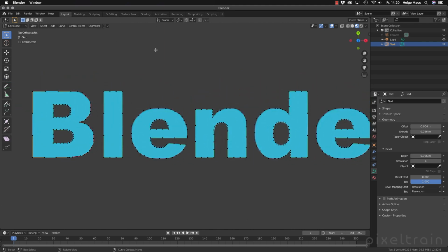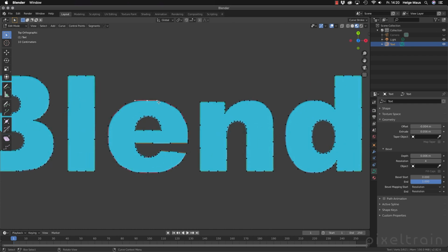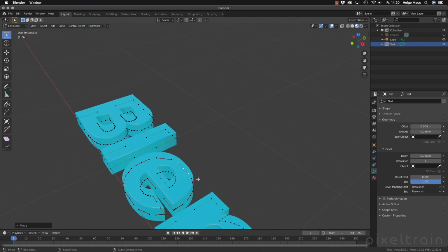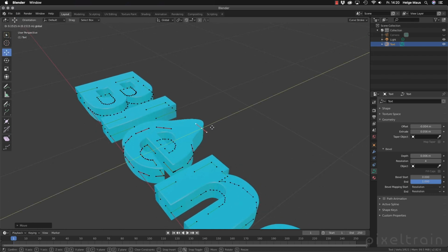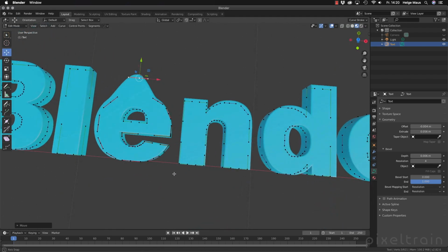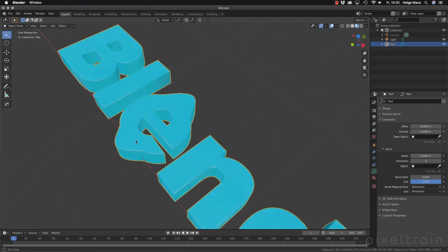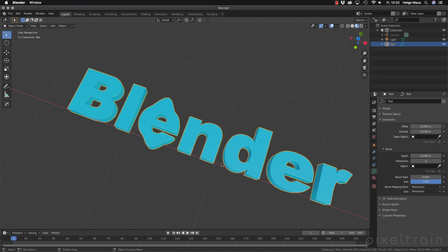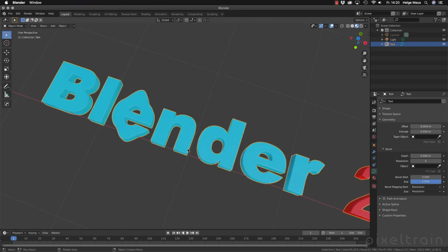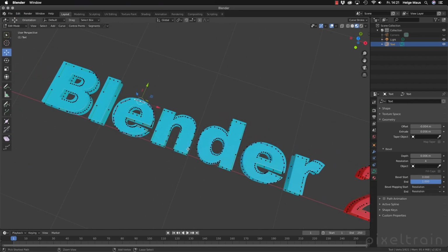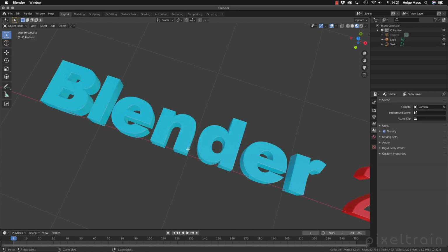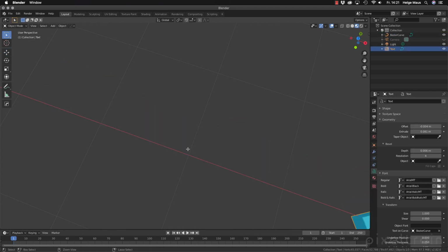And one of the advantages to have it now like that here is if you now go to the edit mode, you are now in the edit mode of a curve. And you can now go here, for example, take this point and you can grab it now if you like. For example, if you now take this point here, grab it out, and you can make funny things with these curves here. So this is one idea of working with that. So curve data. And let's go back here until we are back in the text itself.